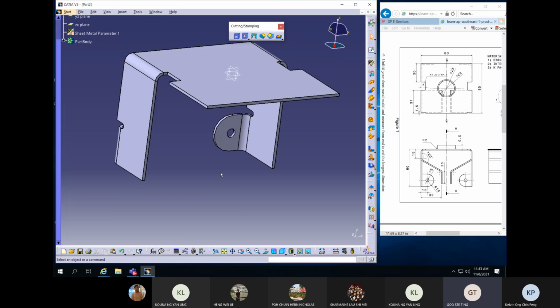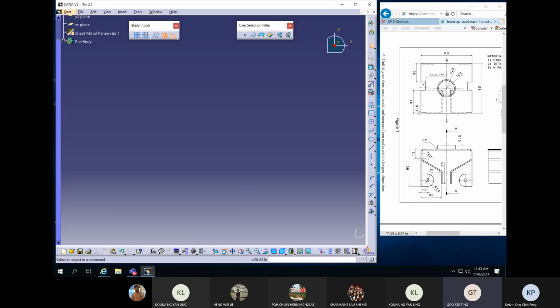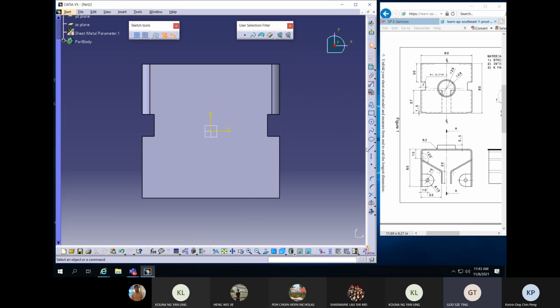Okay, this part here. Remember what I told you? If I want to do user flange, it's easier for me. So for the user flange, I must go inside by another bend radius, right? So basically, I want to cut out here first. Sketcher mode, bring back in. So I want to cut out another user flange. So cut out here, here, here to here is 4.5.